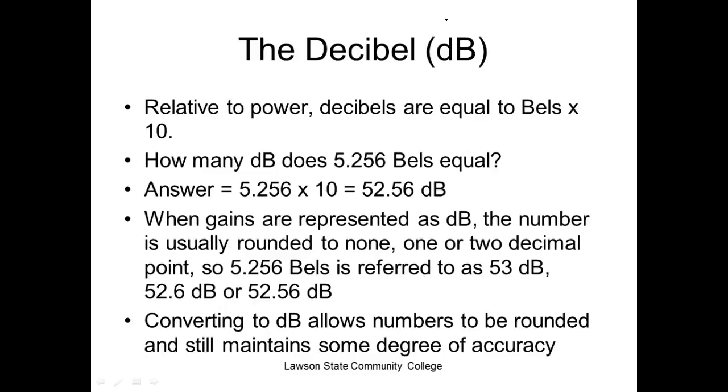If I come up with 1,253 ohms, we would say 1.3K, right? Or something like that. We would round it, right? You understand that? I think in DC, we require y'all to round to 2 decimal points. But when you get into solid state and AC, we drop it down to 1, because it's accurate enough. But we understand that.